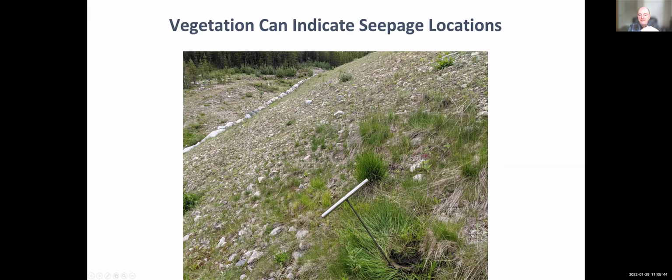Where you have a pretty dry, arid environment on your dam, and suddenly you start to see things growing, it's an indicator that you do have water in the embankment, and perhaps seepage and maybe an elevated water table through your dam.